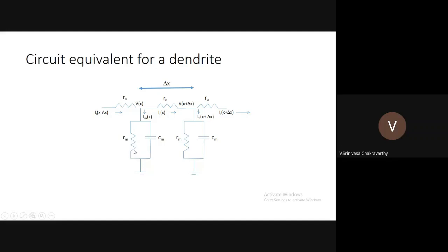Since both circuits will have a battery of the same value, called V rest, the resting potential of the membrane, what we'll do later on is redefine the membrane voltage so that we include this resting potential. So we do a coordinate transformation and get rid of the battery by redefining the voltage, which will take care of that baseline voltage. Therefore, you just understand that this is included. It will be taken care of later, so we'll remove it right now.